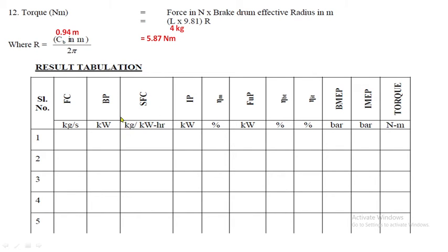because you may ask, what is the fuel consumed per kilowatt hour? Keep on increasing the load, the fuel consumption per kilowatt hour of power production will decrease compared to all other parameters. After calculation you may check whether it is increasing or decreasing. Each and every numerical value has a concept behind it. You can correlate your concept with these calculated values in the result tabulation.